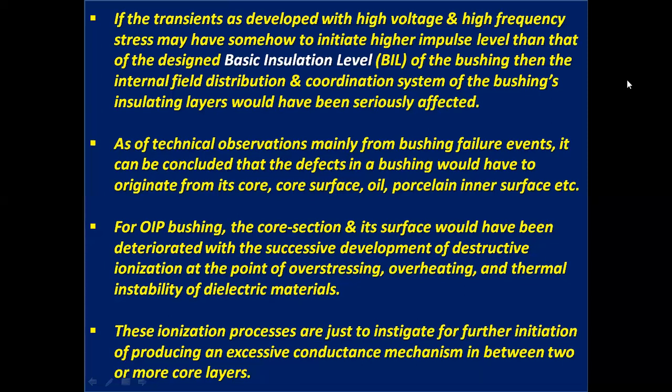For oil impregnated paper bushings, the surface of the core section would deteriorate with the successive development of destructive ionization at the point of overstressing, overheating, and thermal instability of dielectric materials.